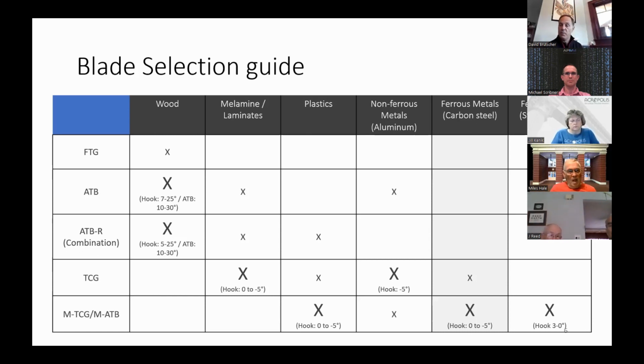Again, it depends on some applications, and then the ATB angle of somewhere between 10 and 30 degrees. Most of the major manufacturers sort of fall into that category. High ATB angles, there's a number of companies that have that, which is great for scoring and low chip out, but it does impact the surface finish of the cut you're making, just because of resultant angles, cutting angles,